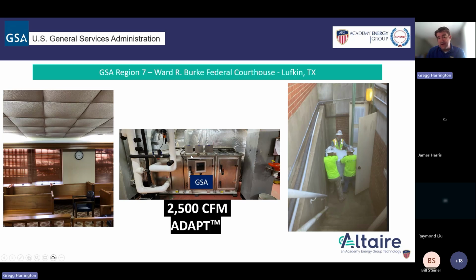And again, this unit had a coil section, a filter section, and this one, because it was feeding multiple air handlers, we had a fan VFD section. And we had to bring it in modules because of the access to the equipment room. So we have the ability to get these things through standard doorways by the way we do our shipping splits.